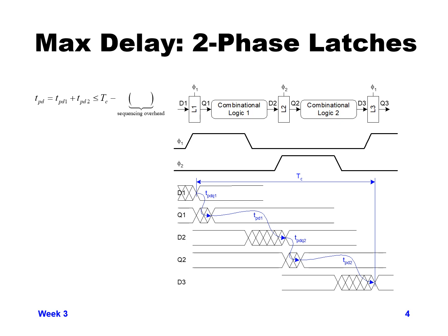But you can see here, because we're trying to get through each latch around the time that the latch is opening, and not trying to force our timing to get to the latch before it closes, we don't have to worry about the setup time to the closing edge of the latch. This is a way to only be dependent on the propagation delay through the latches and not be dependent on the setup time like we had with the flop.